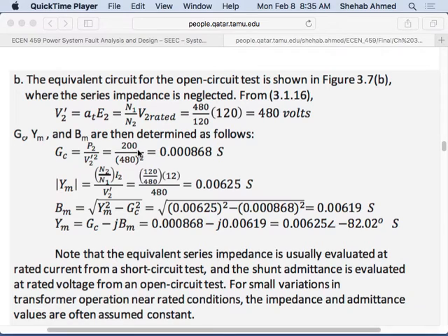So real power divided by the voltage squared, I should be able to get the conductance portion of the admittance, right? Admittance is divided into conductance and susceptance, right? So the real power is dissipated in the conductance, right? So I was able to calculate my conductance, the resistive branch, and we go through the same process. So if I know my conductance, and I know what else? So how do I calculate the admittance?